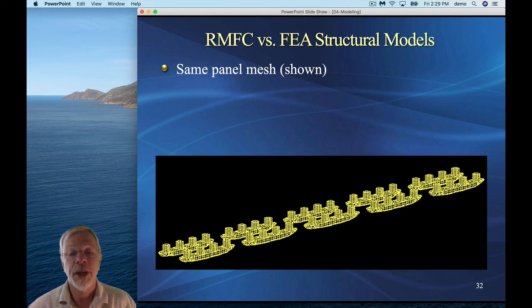That means that each module is rigid and has 6 degrees of freedom, and there are 5 modules, so the entire system would have just 30 degrees of freedom. A more detailed finite element structural model is going to use far more degrees of freedom than that, and we would need to use a reduced basis for that sort of a model.